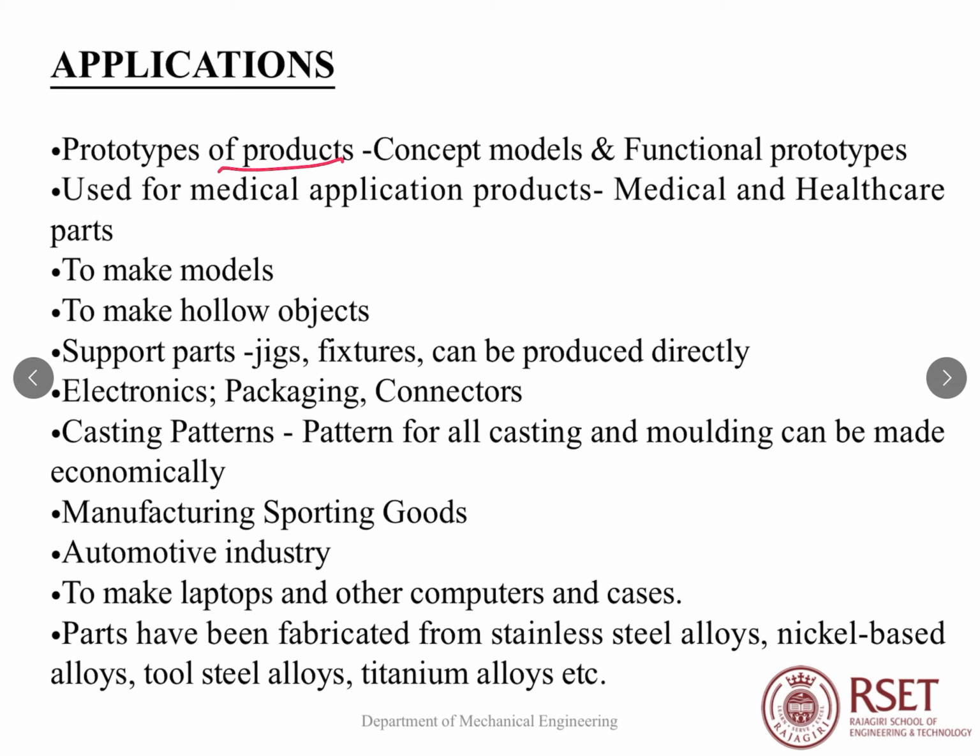We found that it can be used for design verification, validation of a concept, and fast production, but it has certain disadvantages. Size limitation is there, strength limitation is there. Some components and support structures are difficult to prepare, but it has found application in many fields.